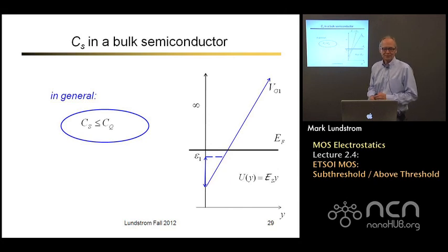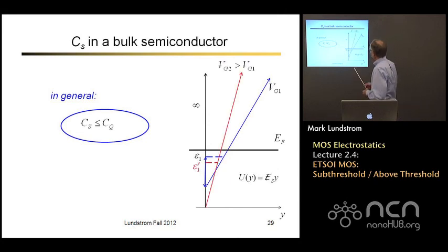And why is that? Well, that occurs because when we increase the potential, we pull the bands down, that's the red line. That's just what happens in the extremely thin SOI structure. But we also make the well thinner because the electrostatics squeezes the potential well. The fact that we make it thinner pushes the first confined state up.